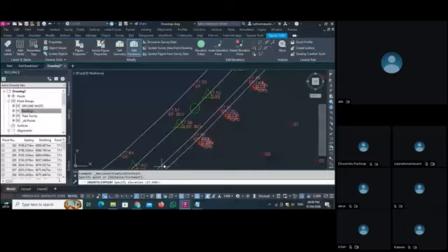Then they ask us, what is your elevation on this point? Our regular elevation is 17.540 here. So if you want to provide the same, you can provide the same. If you want to change, like I want to do 18, say 18 and select OK. If you want to do an increment, or if you want to make any distance point, you can provide a distance too. So this is the workflow.